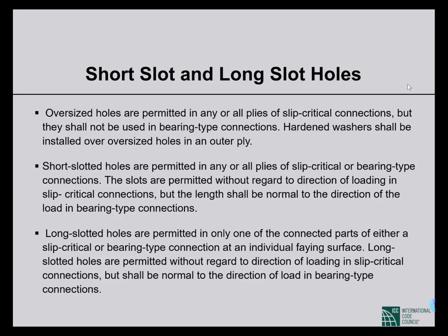So that's a requirement. Long slotted holes are permitted without regard to direction of loading in slip critical connections, but shall be normal to the direction of loading in bearing type connections. So the same thing is applicable here also for long slotted holes, that the elongated side must be perpendicular to the direction of loading.